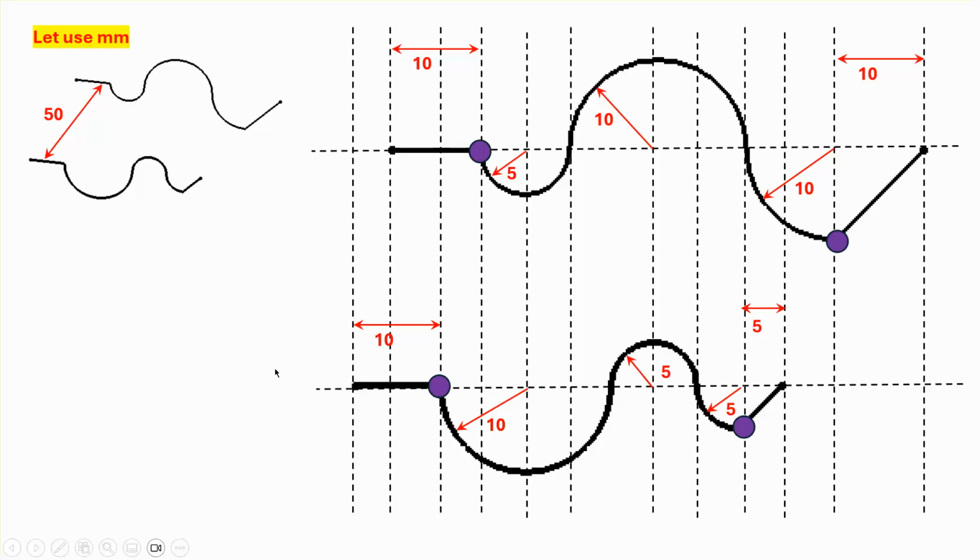And notice that at these 4 points, there is a tangent discontinuity. Okay, when you say tangency, what is really referred to, meant in 3D Experience CATIA or CATIA V5, is the discontinuity in tangency. So these are the 4. And there are 2 which are discontinuity in curvature.